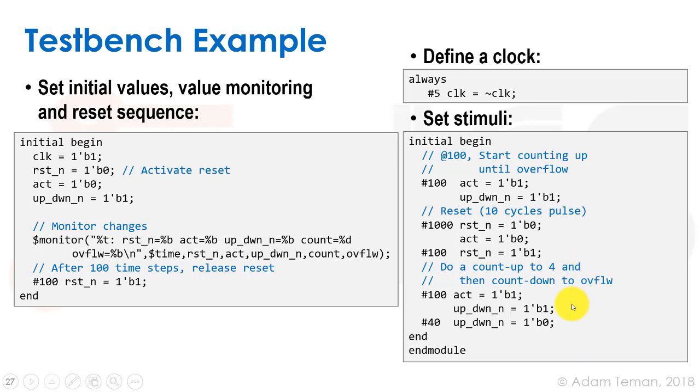So that's a way we basically tested almost all of our signals, or hopefully all of our signals and all of our states in our state machine. That is called a directed test. It is not a formal verification. It's not even a good type of verification, but it's what we want to just do to test that at least our basic functionality works.